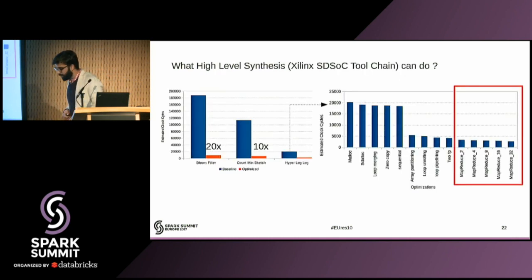Now, this is also a very interesting slide, because if you talk to people from industry, they would claim 20x, 100x performance improvement or acceleration with FPGAs. And what I'm showing is that by using high-level synthesis, yeah, you could actually get 20x, 10x. But what you always need to ask is, what is the baseline? Because if the baseline is not optimized, for sure you could get 20x.